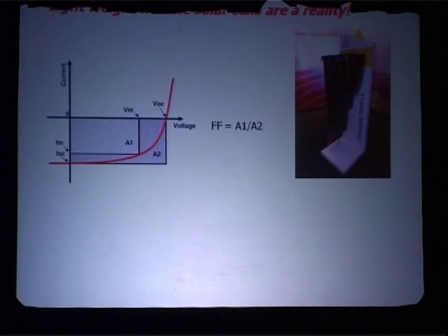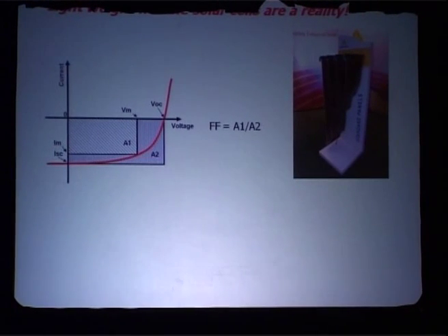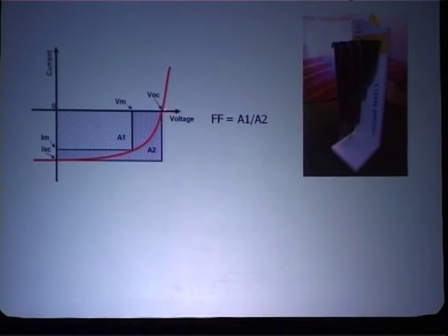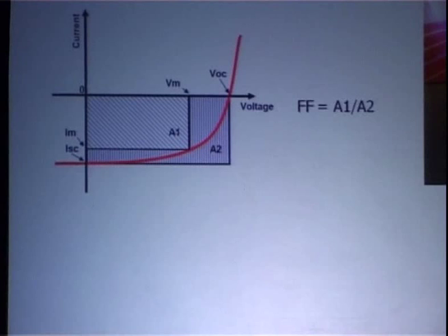This is a plot of the kind of data one expects to get, current versus voltage. In the dark, of course, this is a diode which has nearly 0 current and then turns on in forward bias. But when you shine light on, one gets photogeneration of carriers. One collects them at the electrode, and you get a short circuit current because of the built-in potential that comes about from that heterojunction. And then when you change the voltage, you compensate that internal voltage with an external voltage, and at some point the current goes to 0. We call that the open circuit voltage.